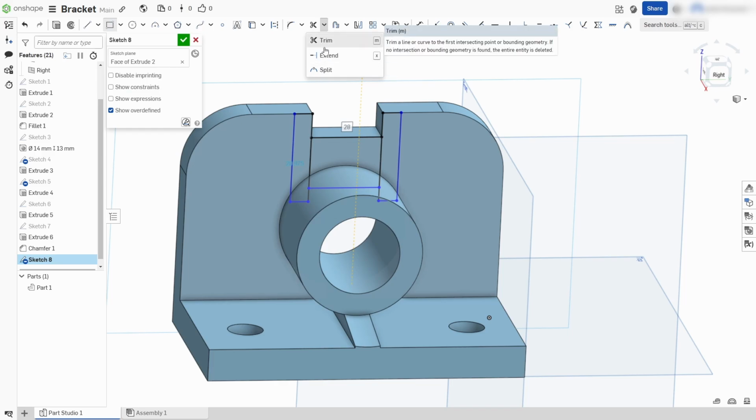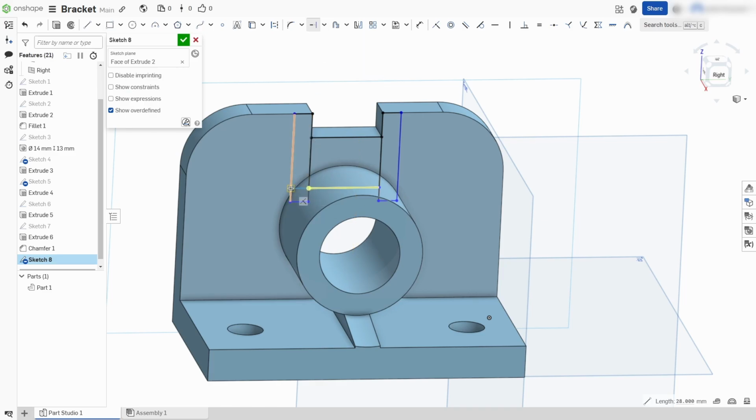So right now we want to extend this line into here. Okay. Extend this guy to here. Oh, it's cut, so undo. Control V. And we want to extend this guy to here. Okay. And then we can trim. I can hit the M key if we want to do it. Yeah, this is easy. Okay. We can get rid of this.